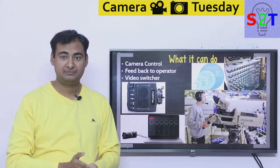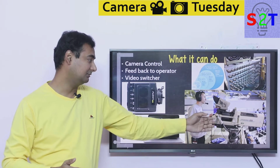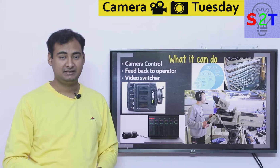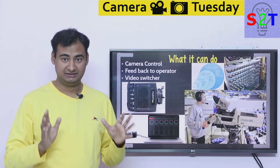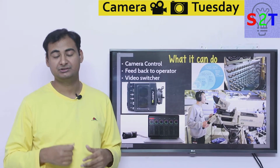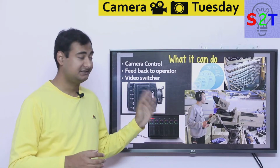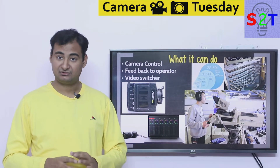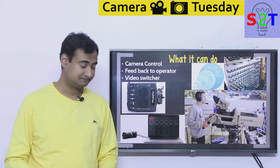This is why your Red Epic, your Canon C200, the Alexa Mini, broadcast cameras, Blackmagic, everybody has SDI. SDI is a whole different level of thing. In production, you can't bypass this. If you want to do a live telecast reliably without pulling your hair out, and if you have a multi-camera setup, SDI is the only option. If you try to do this with 4 cameras using HDMI, it's not that you can't do it or there is no equipment, it's just you're gonna pull your hair out.